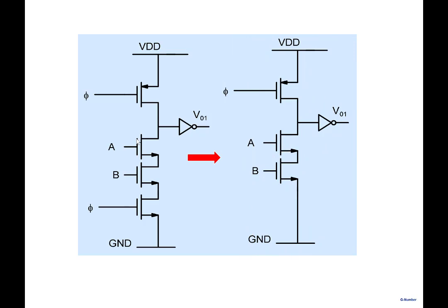Another way in which you could solve the problem of cascading is by, before that, some people also try, in order to improve the speed of the transistor here, to remove this particular transistor here, the lower transistor. That has been removed because, remember, the more transistors you add, the more the pull down strength decreases, and the longer it takes to pull the node back to 0 here.